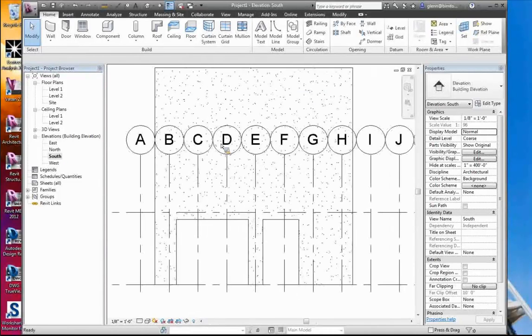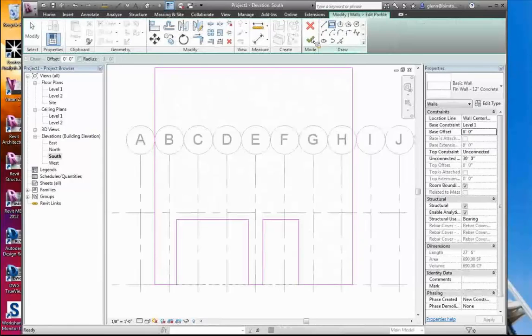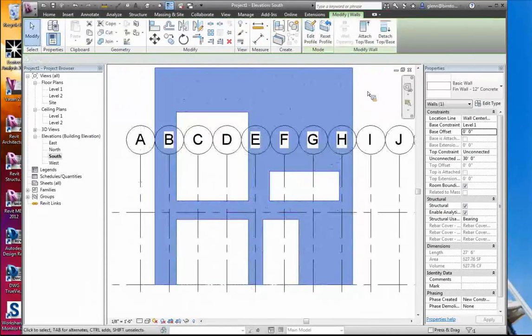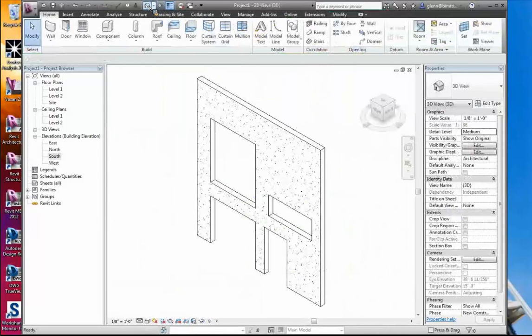If I was doing this house, I would probably do something like this to create the fins. I'll edit the profile. Maybe I can put in some of those big openings that are up on the second floor level or on the roof level, whatever it is. Just kind of make some openings to cut the fins. Okay, so are we good on the idea of the fins? Yeah. Okay, so edit wall profile, kind of make those fins look the way they want to.